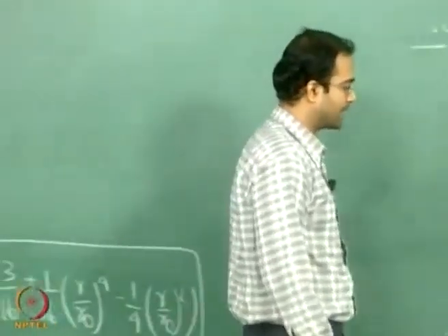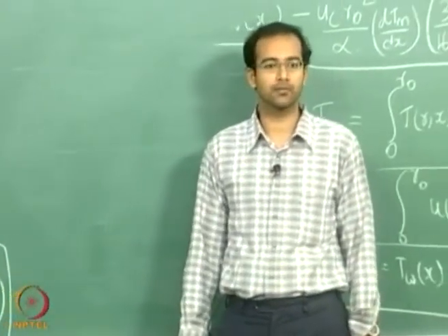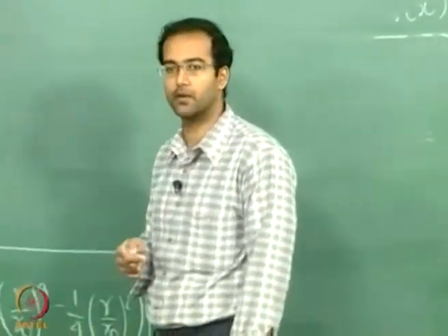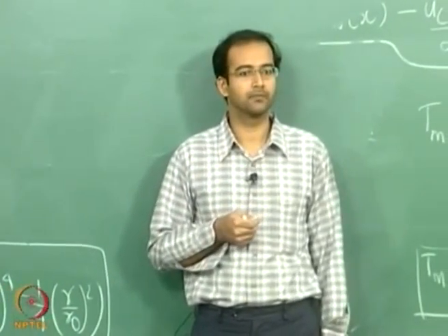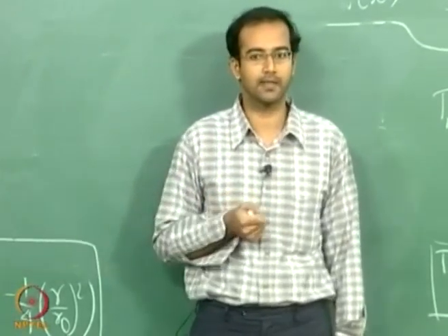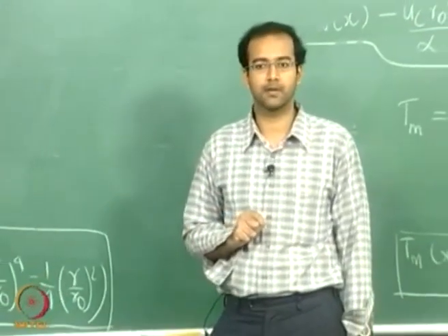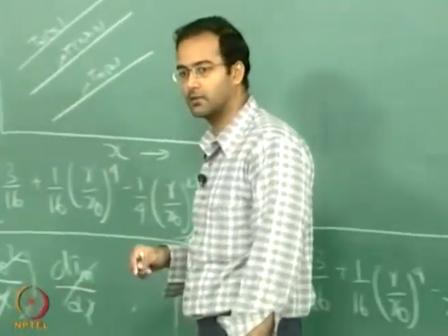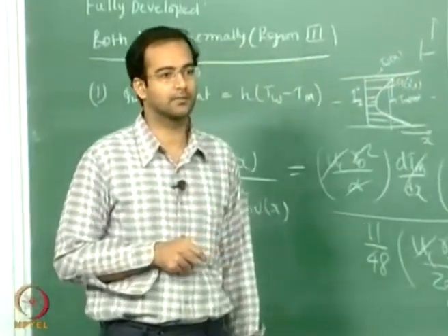Now you can use this definition of theta and calculate your heat transfer coefficient. We had shown that in the case of thermally and hydrodynamically fully developed flows, the heat transfer coefficient has to be a constant. Now we have to determine what is that constant value. So for the constant heat flux case, we have arrived at the particular profile for non-dimensional temperature. So I will probably give you about 5 minutes, you can from this step calculate what is the heat transfer coefficient.